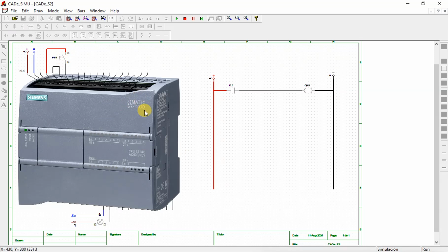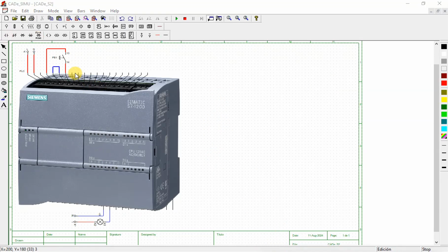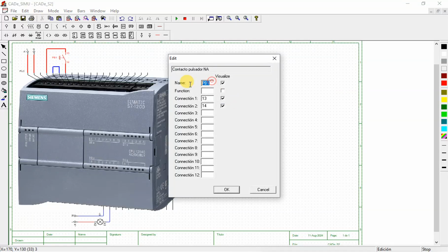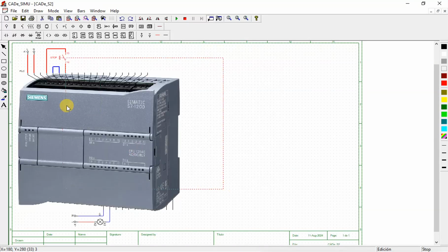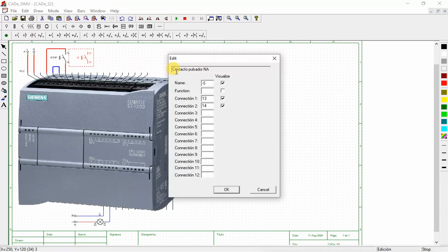That's the basic. It applies to most of the PLCs. Now let's try to see how to power a motor direct online using this PLC of ours. So this setup is going to remain like that, only that I'm going to have this button. I'm just going to name it stop, and we are going to have another push button. Allow me just space it to look neat. This one I'm going to name it start.